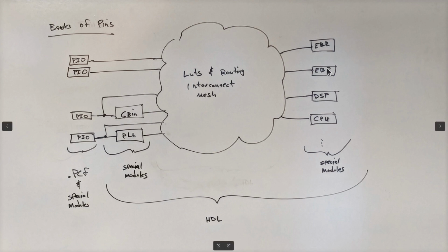There's a couple of dozen of these things inside the HX4K chip, and we will use them if you want to. You can use it to create a FIFO, or if you're going to create a small CPU or something and put it inside here and express all the functionality of the CPU with LUTs and stuff. You can use these as a cache, or you can use them as your register file and stuff like that. Hopefully, we'll get to the point where we can do that in this series. I'm very excited about tinkering with that myself.